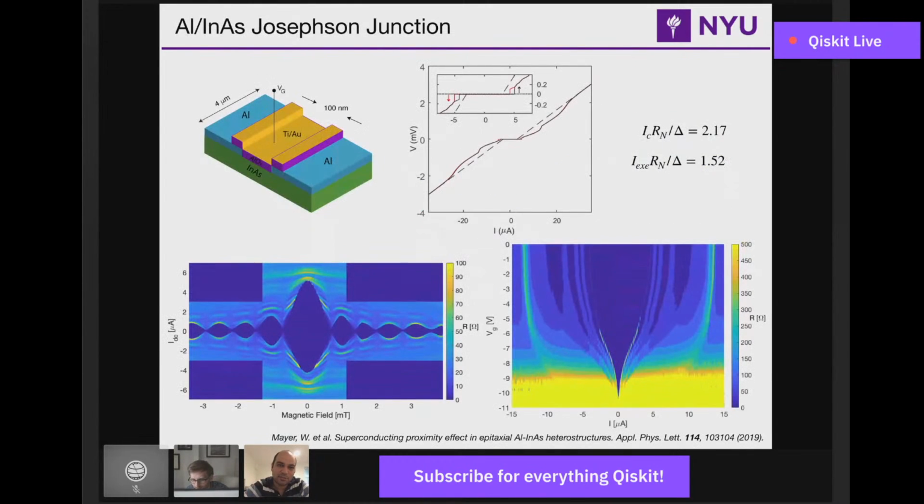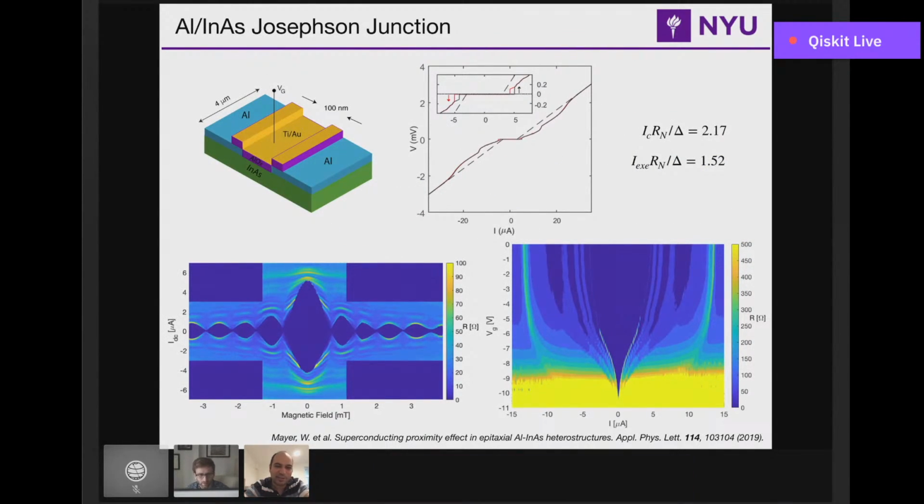Yeah. So then you obviously have this material as a 3-inch material. You can make Josephson junctions out of them. On the top left, you will see a schematic of it. You basically remove the aluminum to form the channel. Now the Cooper pairs have to travel through the green indium arsenide and back up to aluminum. And if you want to have the gate dependence, you have to put a dielectric like aluminum oxide and then a gate on top, right?